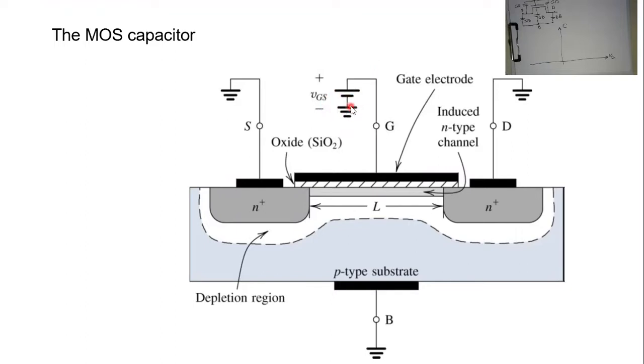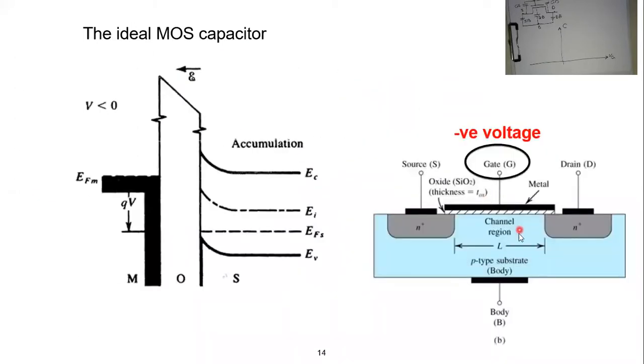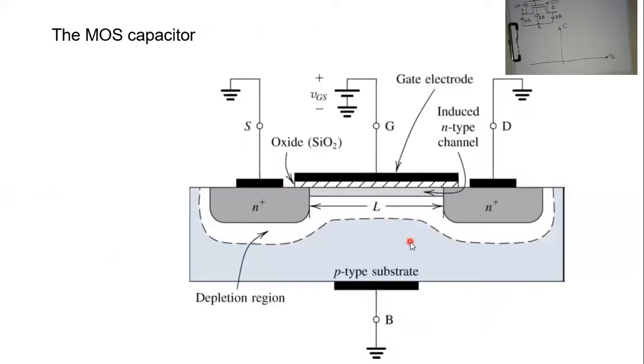Because whenever you have a voltage greater than V threshold, then you have this N type layer, and then this PN junction starts to occur. However, if you apply a negative voltage here, that means that this substrate will still be a P type. So there is no PN junction here. That's why there is no capacitance. Accordingly, this depletion capacitance, or the CD, occurs if and only if you have a positive voltage on the gate. Otherwise, you don't have a CD.